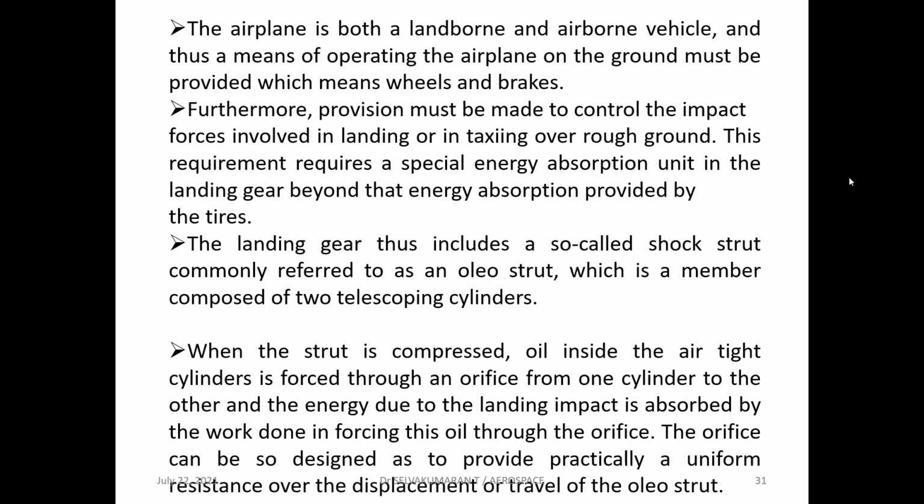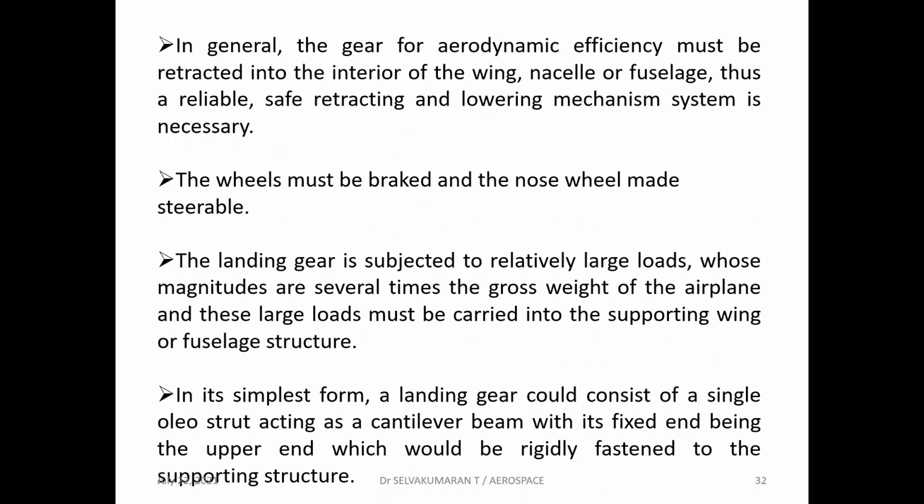The orifice can be designed so as to provide practically a uniform resistance over the displacement or travel of the oleo strut. In general, the gear, for aerodynamic efficiency, must be retracted into the interior of the wing, nacelle, or fuselage. Thus, a reliable, safe retracting and lowering mechanism system is necessary.